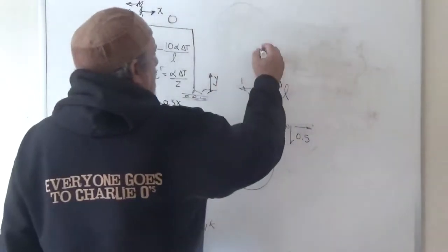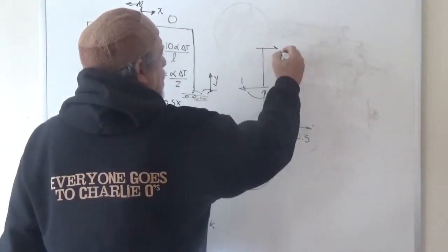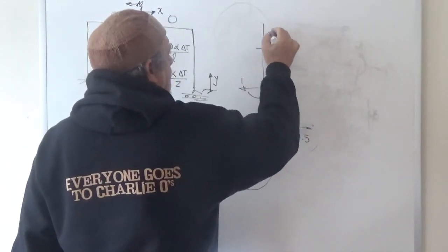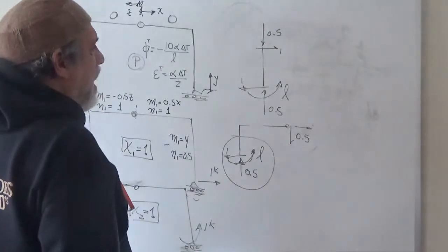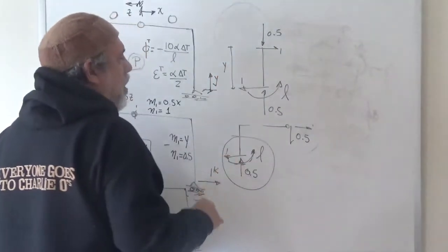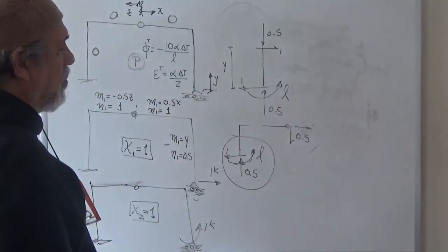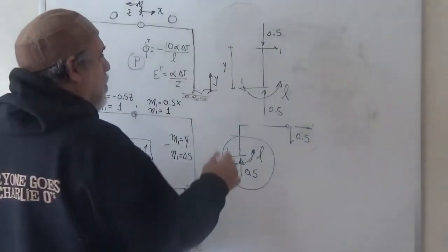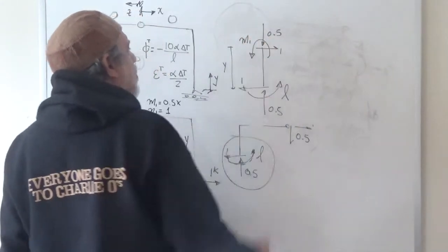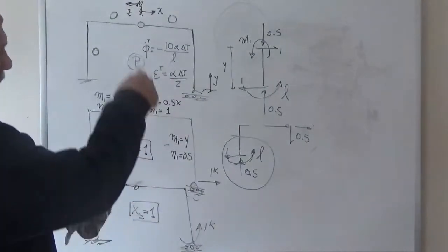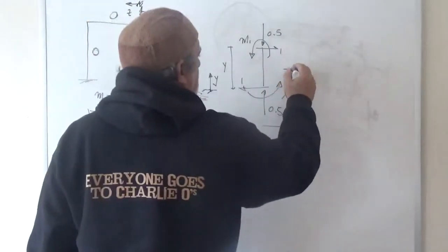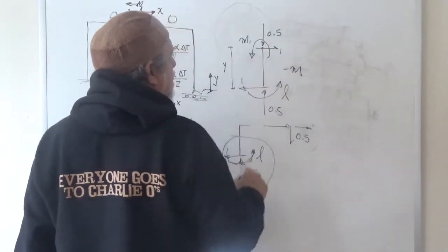And so here we have our cut, and so there is a shear, which will have to be 1. There is an axial that'll have to be a half in that direction. And there's going to have to be a moment. Now the distance from here to here is y. And we're going to have to assume some sign for the moment, but we already decided. Our moment is selected such that it produces compression on the outside. And so that's M1. If I look at that bar, I go like this, I put compression on the outer fibers. And so I say minus M1, summing moments about here.